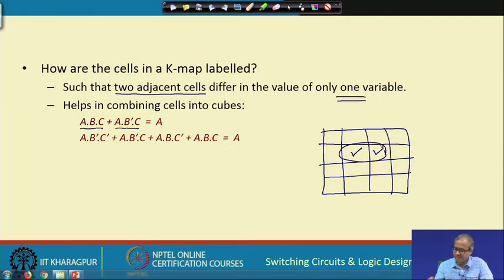So, the idea of combining is this: if I combine them, then by the rule of simplification, if you take A C common, this B and B bar will cancel out, and this will be A C. Okay. So, if you take A C common, B plus B bar, this will be A C. So, there is a minimization.